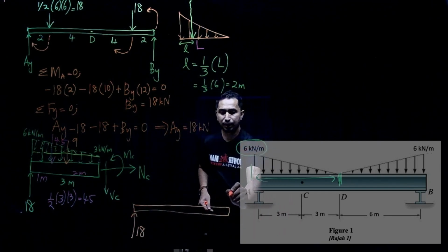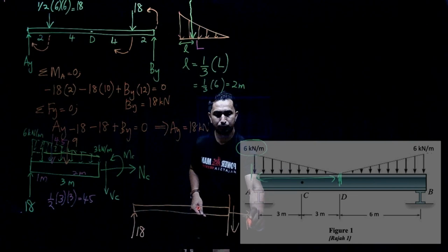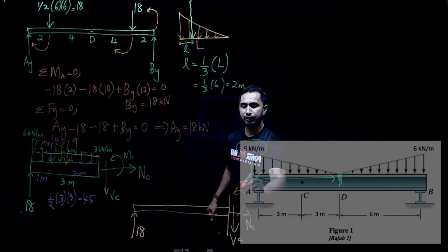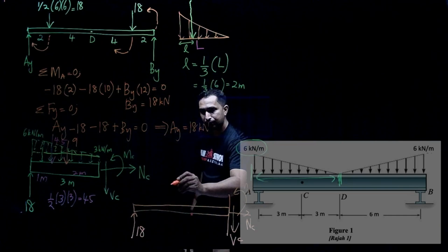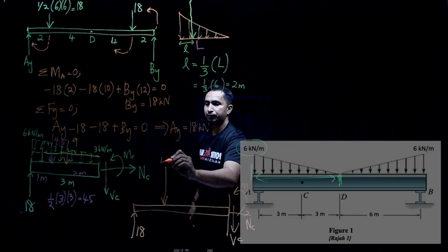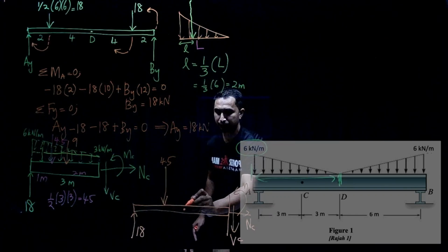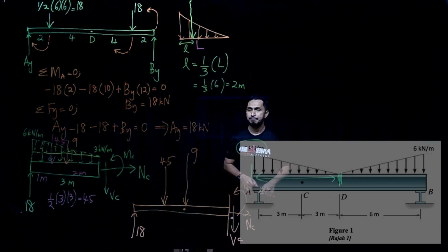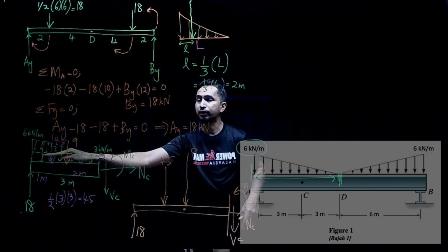Then we cut here, we have that three things: normal force at the point C, shear force, and also here, bending moment, point C. And then over here is 4.5, the triangular shape. And then in the middle, here, I have another force, 9 kilonewton, which refers to the rectangular shape, the lower area.